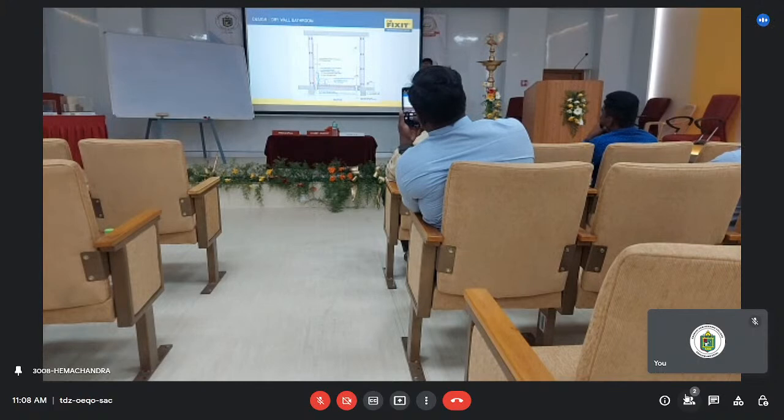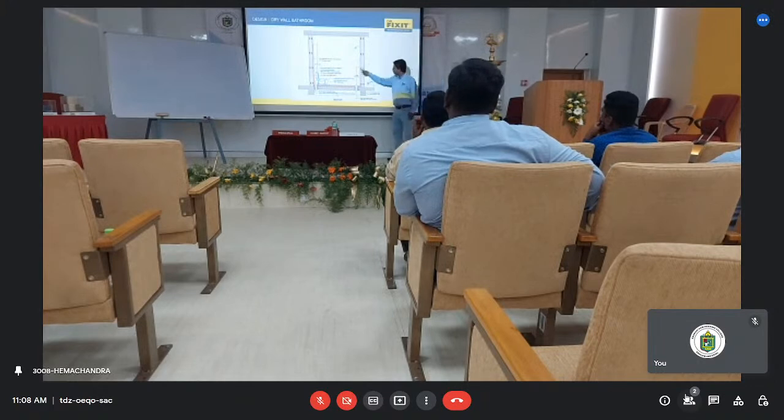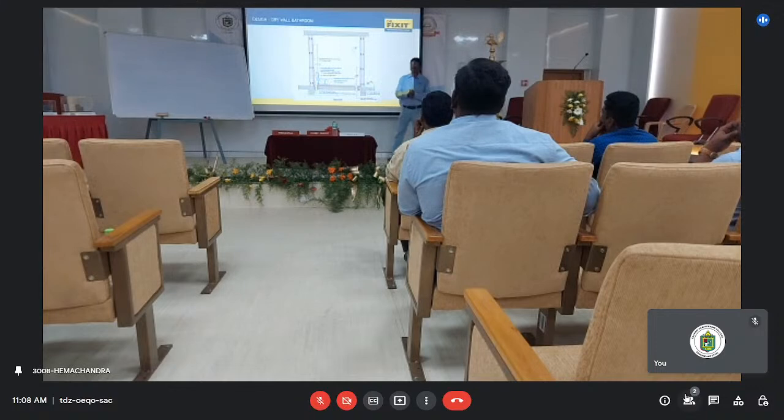Now the technology is precast construction, modular construction, and drywall construction. So there will be panels, and there will be a 5 mm gap between the panels. As I told, the cementitious coating's crack bridging ability is only about 1 mm.